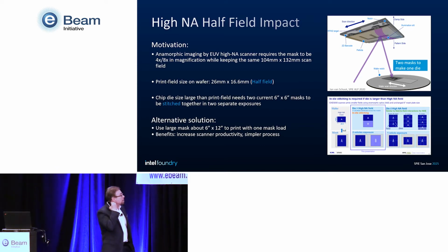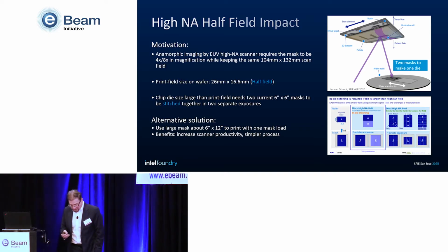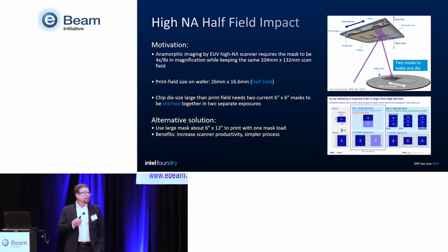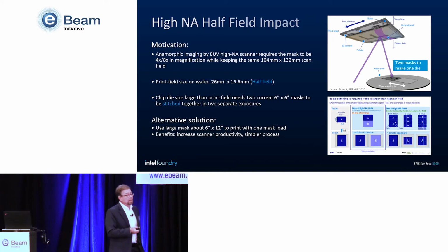About 10 years ago or so, when the designers were working on the High-NA machine, they faced a challenge. As the NA increases, the NA of the mask also increases, and that's a problem, because the NA of the mask is the High-NA divided by the magnification.